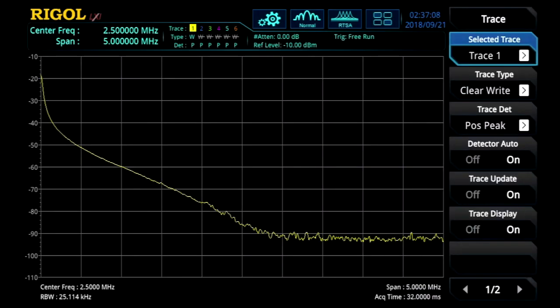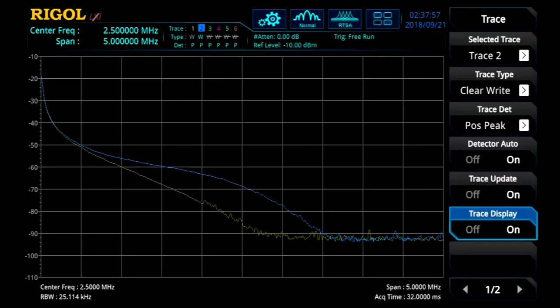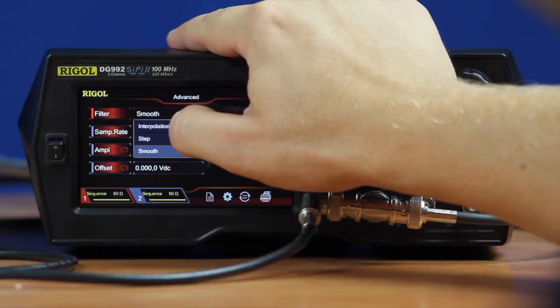Now let's look at those same 3 filtering modes, but what they mean in the RF space. So here we have a real-time spectrum analyzer with about a 5 megahertz bandwidth. So this is DC to about 5 megahertz on the screen. That's our step function, which produces a pretty sharp fall off in the megahertz frequency noise range. There's our smooth function, again a little more overshoot, that causes a little more power in the medium, about right center frequency, about 2.5 megahertz range for this particular waveform.